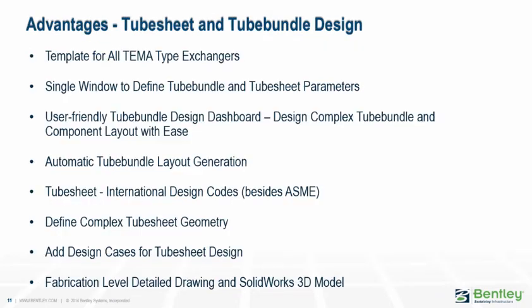There are several advantages of using AutoPIPE Vessel for designing exchangers with complex tube bundle and tube sheet details, which will be evident soon from the videos that will be presented shortly. Some of the key advantages are as follows. First, it supports design for all TEMA type exchangers. The entire tube bundle design can be performed via a single window, which makes data input fast and easy. The same applies for tube sheet design as well.